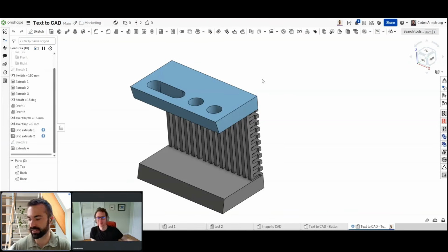Right now, drawings capture metadata that's not part of the model, like the material, the critical dimensions, whether it's plus minus or just plus, or inspection areas. But that doesn't have to be in a 2D format, and I'm excited for a future in which it's not. That's the future of model-based definition. Right on.